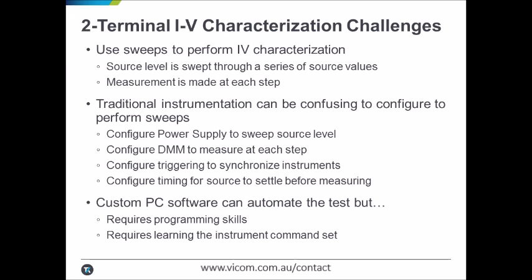Selecting diodes is typically done by configuring instruments to perform sweeps. In a sweep, the source level is configured to automatically sweep from one source value to another in a discrete number of steps, and a measurement is made at each step.